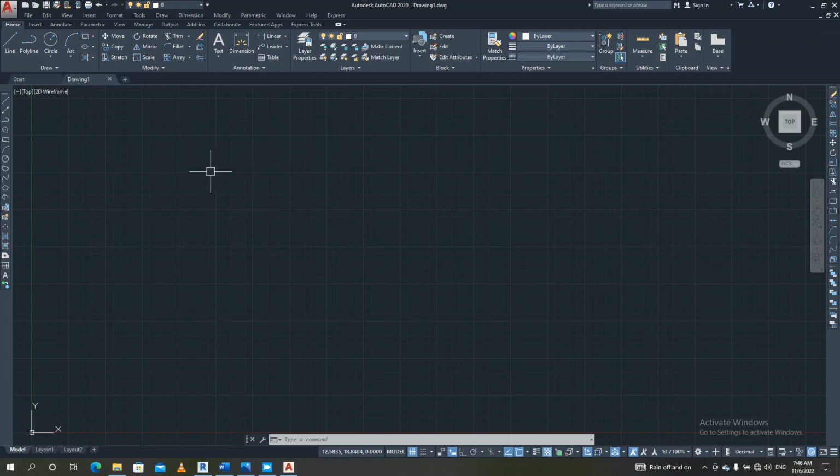All right, how do we set this drawing one page? Drop your cursor in front of your interface and type the word limits, limits. Remember, limits, don't forget the S, it is very, very important. Limits, and press enter button.